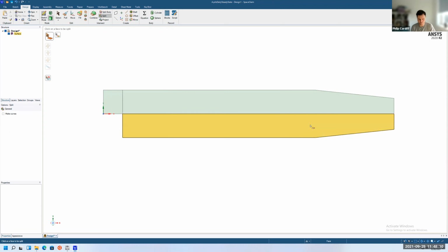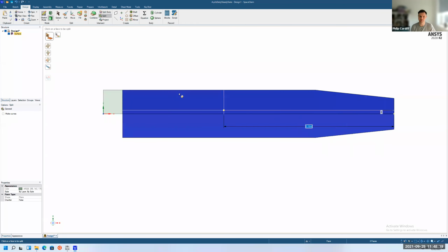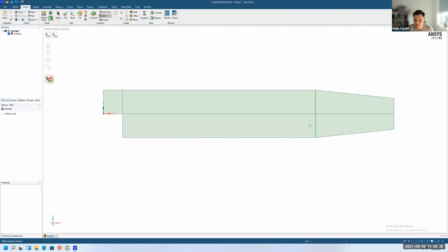So we select this region and, let's press escape actually, split, and then hold control, select the first and the second. And now if we select just there at the corner, that will split across there. So now we have a 4-sided part, 4-sided part, 4-sided part, 4-sided part, and 4-sided part here. So then the mesher will be able to easily put a grid on this.